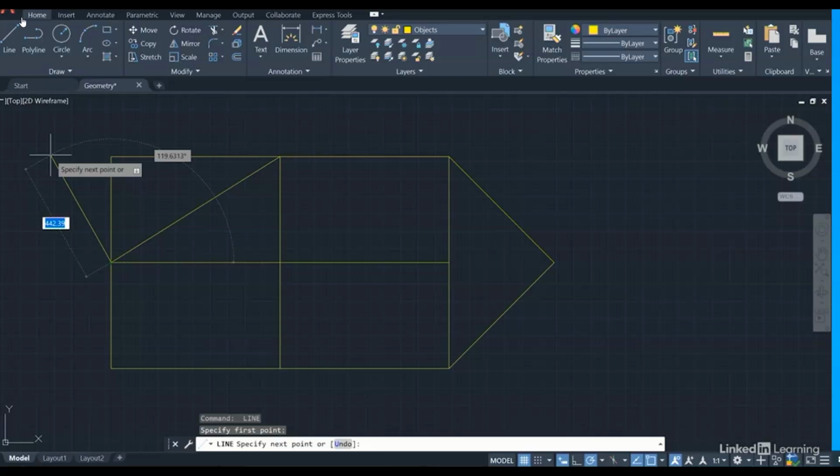Now, I just simply type it in. I type 300, and then a comma, and it automatically knows that I'm putting a coordinate in as soon as I hit that comma key, and it locks that 300 in the x direction. Let's do 300 again in the y direction, and I can just tab between those two values and they then both lock, 300, 300.